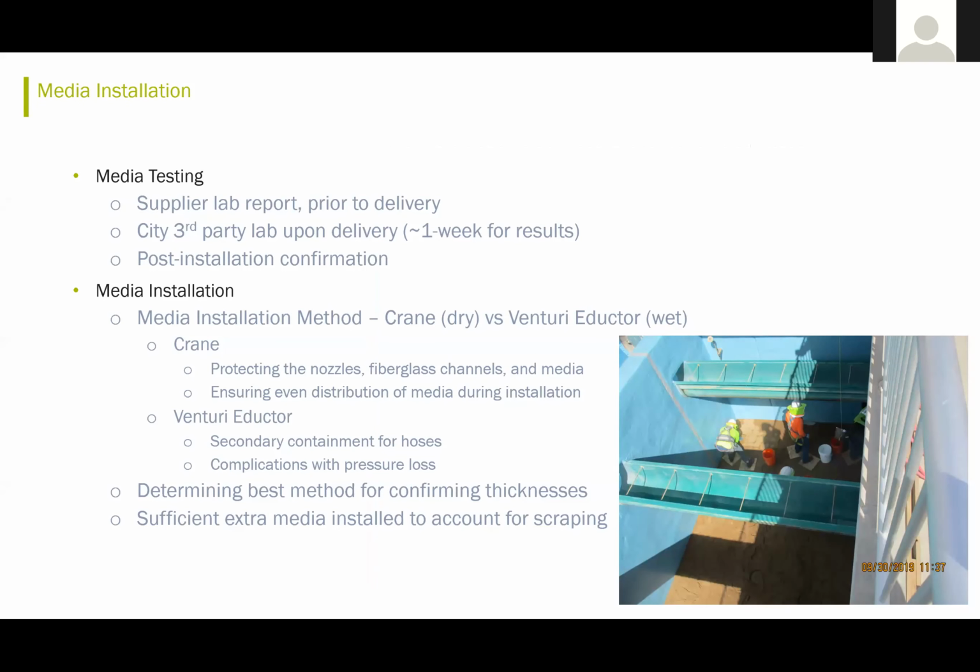So there were some issues with the media installation. The supplier had a lab provide a report prior to delivery, and then the city had a third-party lab, upon delivery, take samples from the media and run sieve analysis and so forth. And then after the media was installed and scraped, they did a post-installation confirmation.